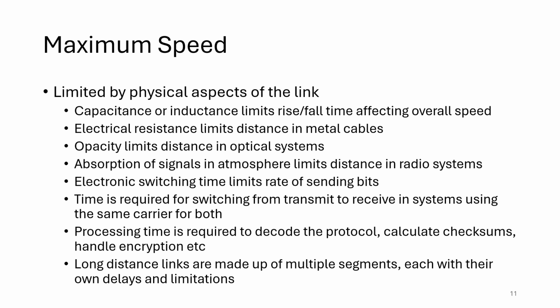And also, as the voltage drops, the cable itself can be more and more affected by noise, which can override the actual signal. Optical systems have longer distances, but they can have limits of opacity in the cable, and that again can limit how far you can send a piece of light across that cable. With both of these, there are mechanisms of having repeaters which can receive data and boost it. But if you've got a very long cable, you could end up needing a lot of repeaters, each of which needs power, and that can cause problems in the physical implementation of these systems.